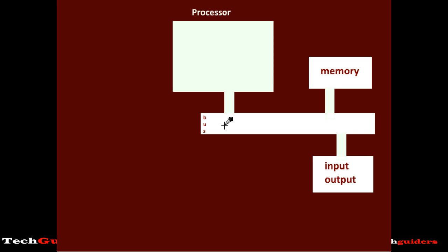So in order to perform these tasks, which functional units are required within the processor? We bring each instruction to the processor, and also if some data is required for its execution, those data are also brought into the processor. But where do we keep them? In order to keep the instruction and the data within the processor, we need a small memory within the processor. That memory can be small since we keep a small amount of data, and that memory should be fast since now we are in the processing phase. That small and fast memory used within the processor are the registers.